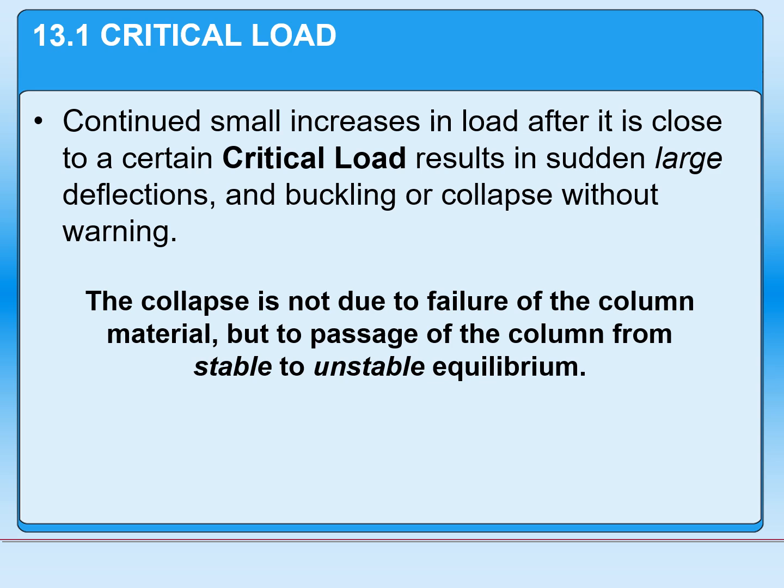Now, it's important to understand that this collapse is not due to the failure of the actual column material. Yes, we have exceeded the yield strength of the material in a small portion of it, but the actual failure is due to the column and the structural failure of that. It's when the column moves from being in a stable configuration to an unstable configuration.